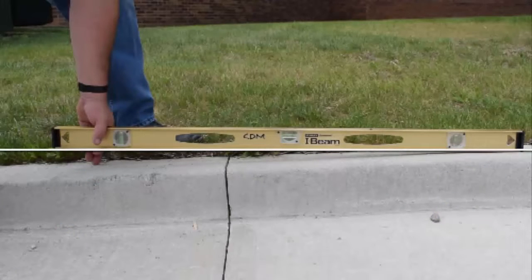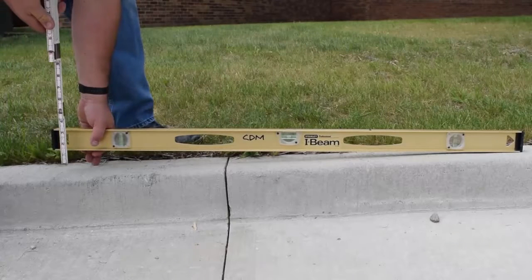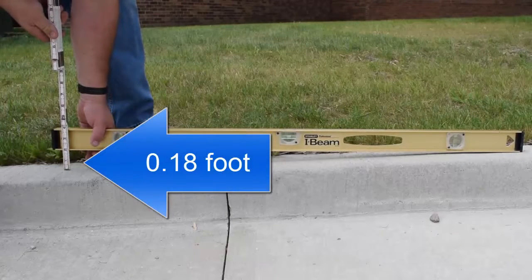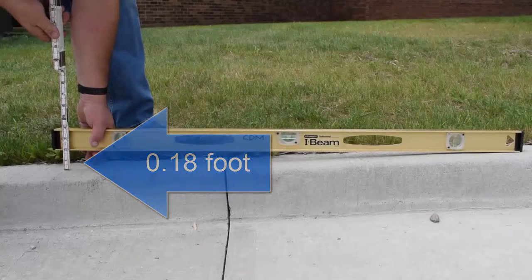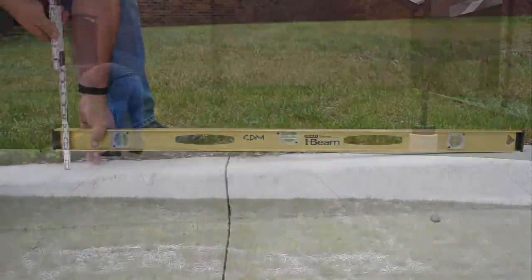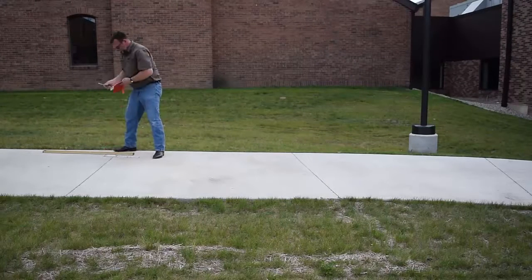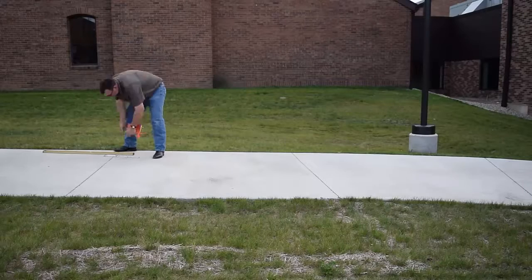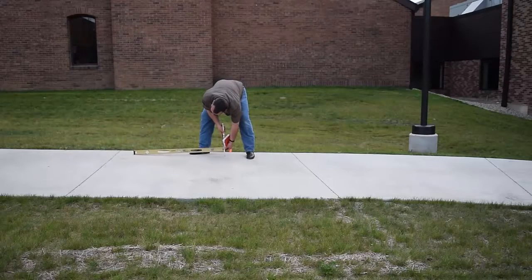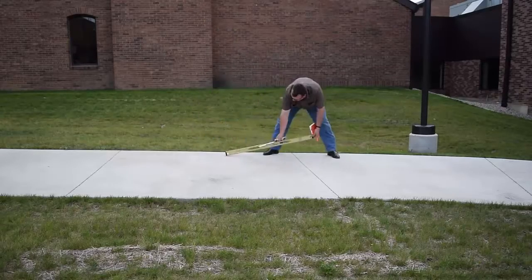With the bubble centered within the marks, I can measure down from the underside of the level to the concrete. This measurement is 0.18 feet. Since the other end of the level sits on the concrete, the vertical distance between the two ends is 0.18 feet. By repeating this process over and over, adding measurements end to end, we can find the vertical distance between two distant points. But that becomes very impractical as the horizontal distance increases.